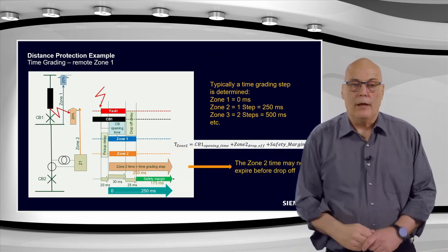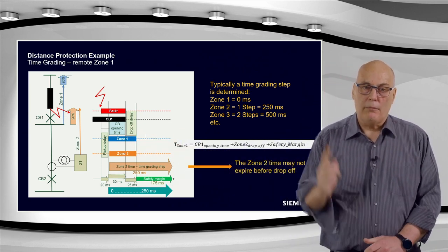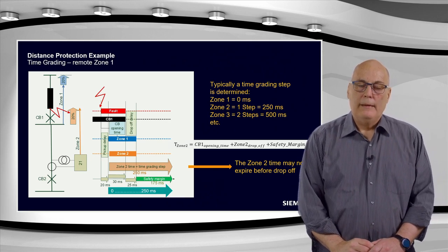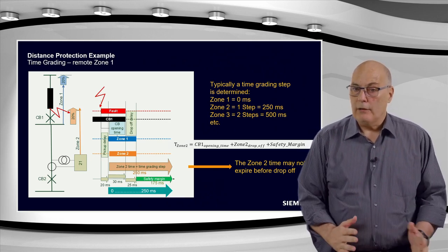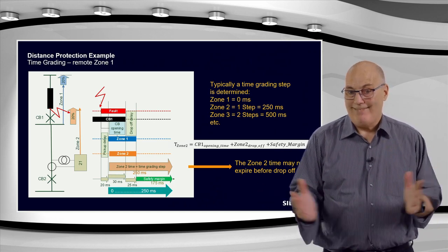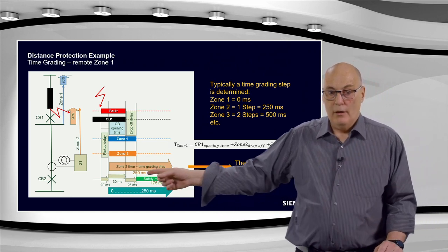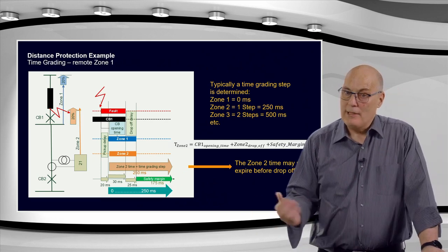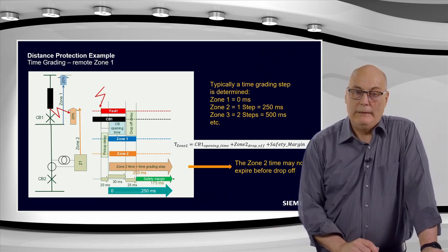So after that 20 millisecond pickup, what is now happening? You see the breaker time here. That is the breaker opening time of that circuit breaker CP1 at the top there. It's while it's opening. And that will take 2, maybe even nowadays 1.5 cycle, 2 cycle breakers in that order. What you can see, I took here 1.5 cycle breaker, 30 milliseconds, a really fast breaker. It could be slower, 2.5, 50 milliseconds, doesn't matter.